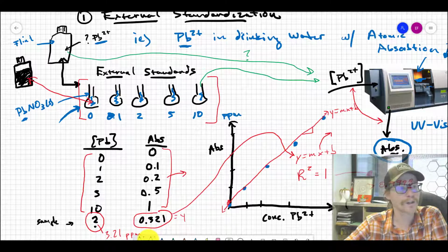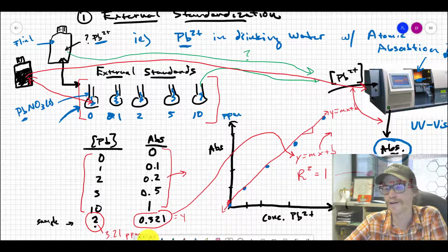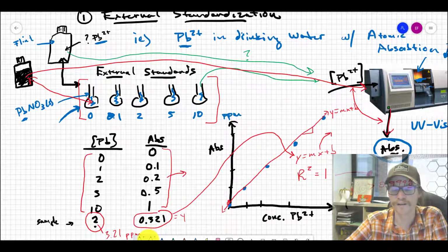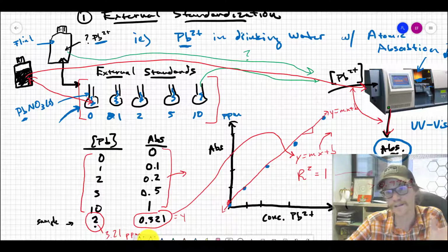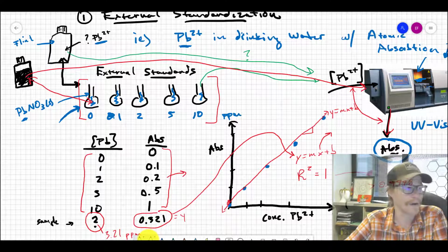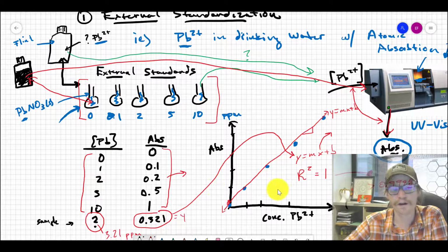And very likely when you take this sludge sample and inject it into your instrument of choice, it's going to respond differently simply because of all the other effects from the matrix that may suppress or may add response. We don't know, but it's not necessarily safe to assume that the response is going to be unaffected by this drastically different matrix.